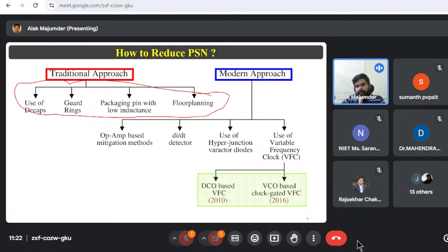At the next timing instant, it is 100 megahertz. Then it will go to another frequency, for example 200 megahertz, then 500 megahertz, like this. And it will reach the maximum frequency at which your circuit should work. If your circuit is working at 2 gigahertz, it will reach 2 gigahertz and settle there, right? So this is a technique people have already used. This is nothing new we have proposed. It is a technique already introduced by IBM, right?